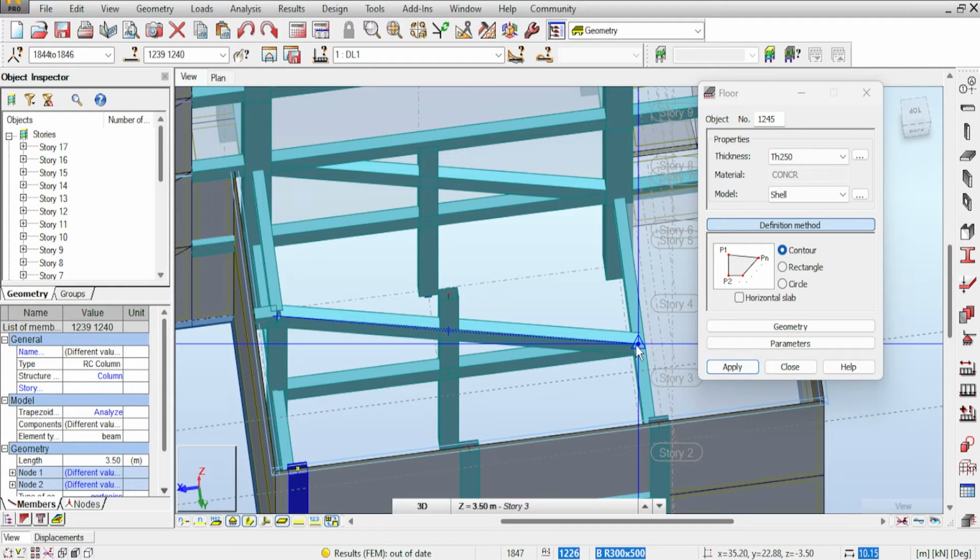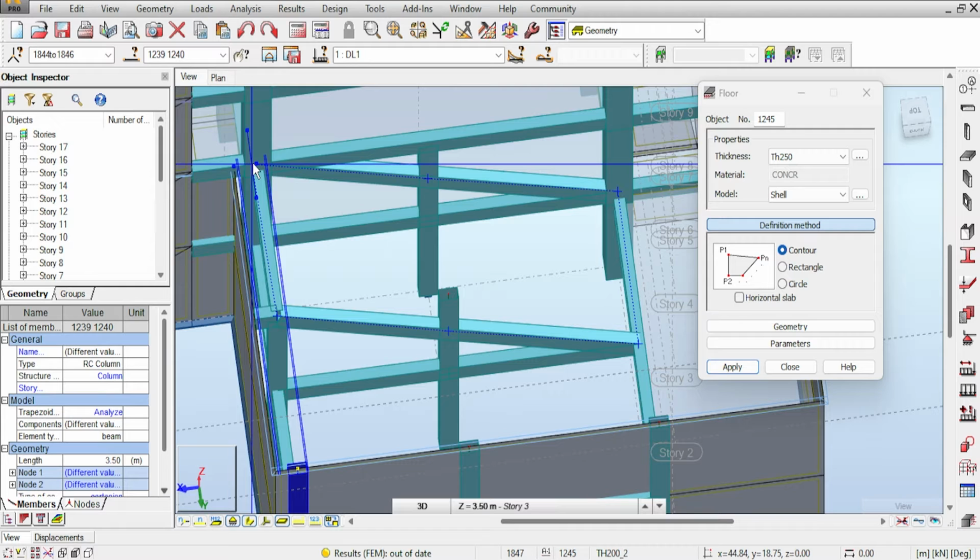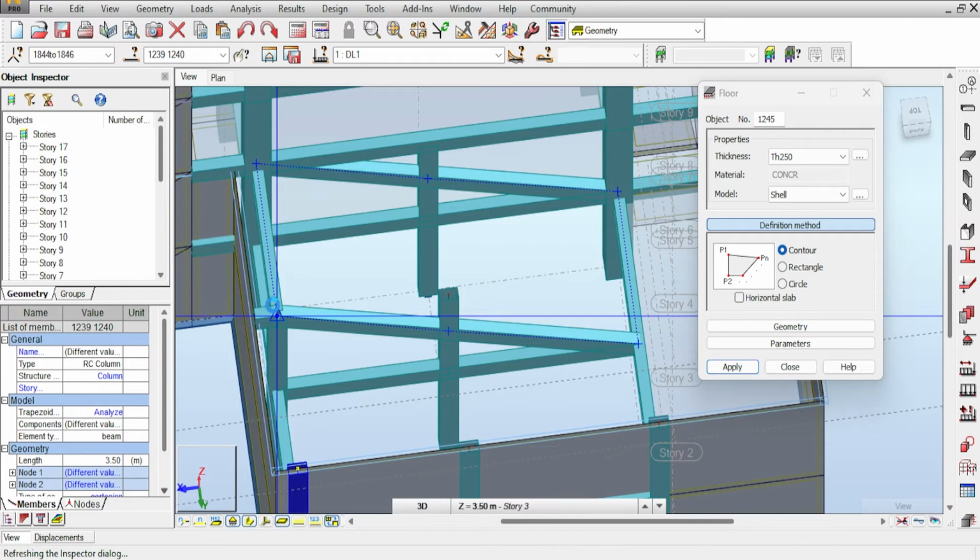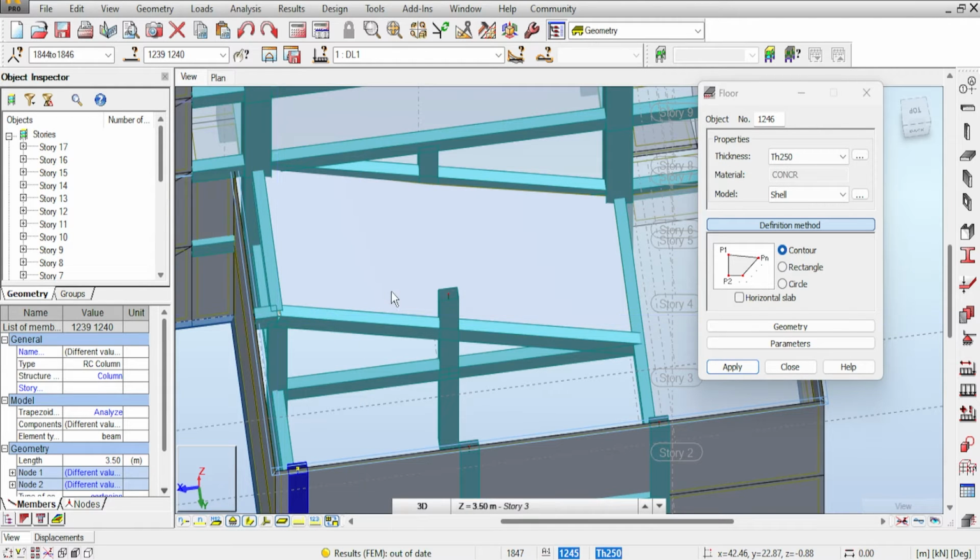And I want to tell you the weaknesses I see in this ramp so that you have an idea why I'm annoyed. The ramp, first of all, is too small. The turning area is too small. And even something else that just occurred to me is the headspace here. The clear space, you have beams that are dropping.